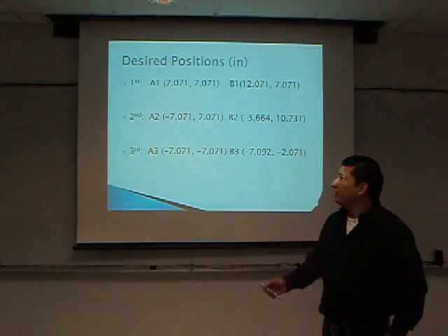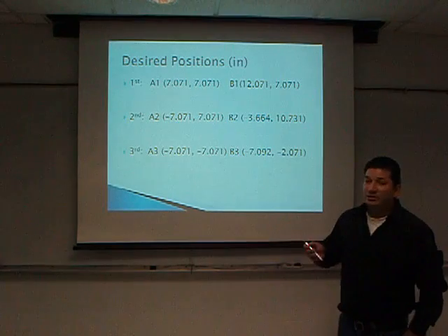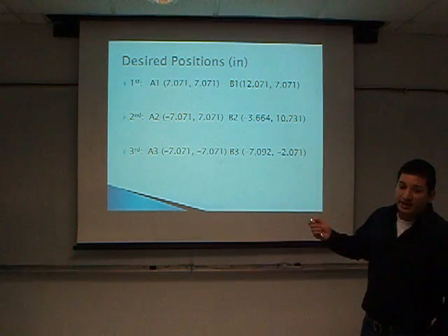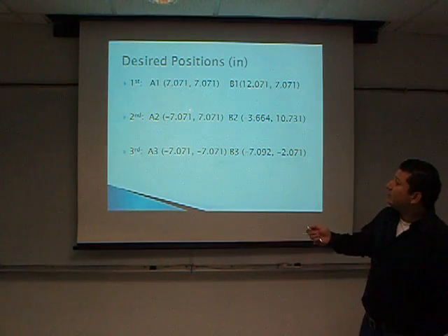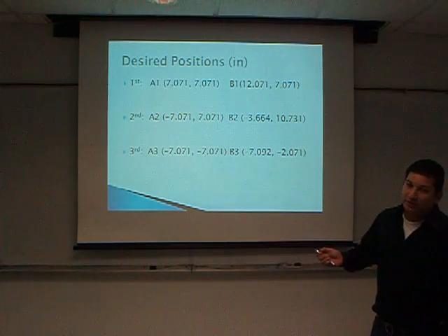In our case, we have three initial positions, which is line AB that lies on the coupler link. The first one is this coordinate, which has 0 degrees of inclination. The second one has around 47 degrees of inclination, and the third, 89 degrees of inclination.